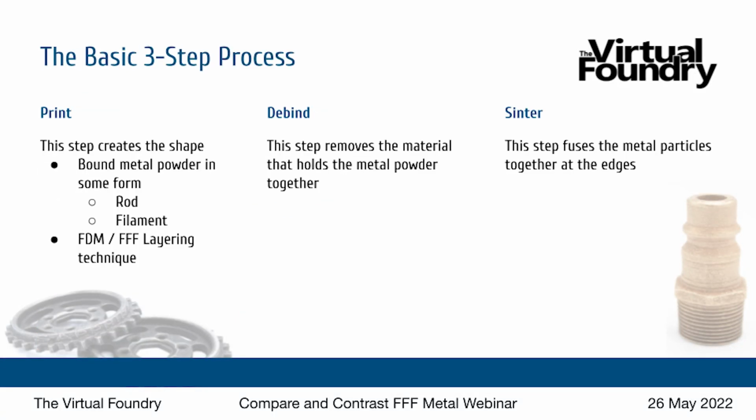First of all, that basic 3-step process that every one of these FFF metal technologies uses. FFF is fused filament fabrication. Another term used is FDM, fused deposition modeling, and some folks also call it bound metal deposition. They're all three using the same basic 3D printing technology.